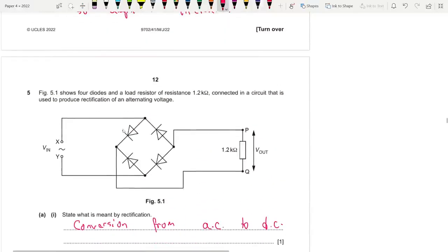Great. So let's do that. What if this terminal was positive? This goes out here. So now which diode should we choose? We can't take this, right? So we need to take this one. Now we can't take this, so we need to go down, right? So we're going down here. So this is our positive terminal, this is our negative terminal. So if you go out now, which one should you take?